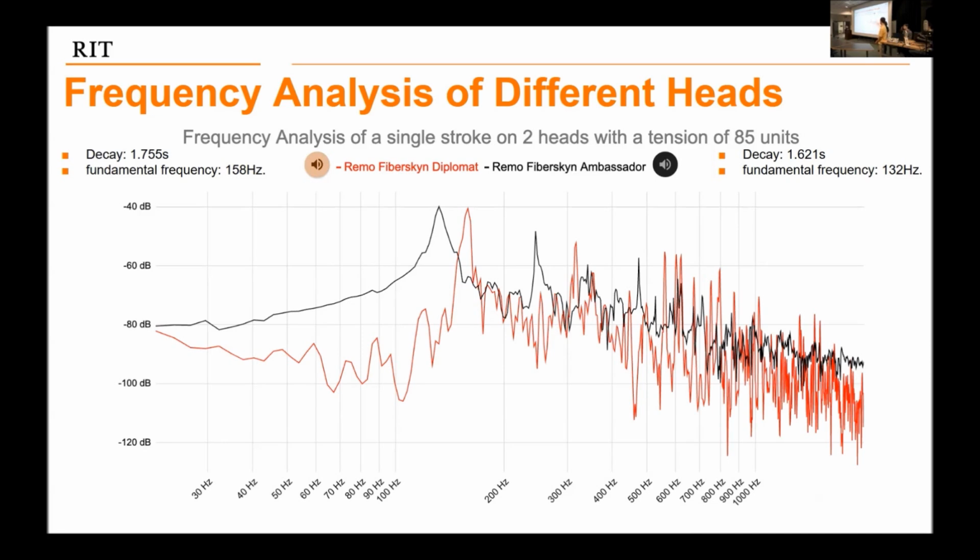So Audacity, I believe it was doing an FFT. Yes. I exported raw data points from what Audacity gave me into an Excel spreadsheet just so I could have a cutoff at like 2,000. Okay. Yes. Yeah, because Audacity does do roll offs. Yes. And you can pick your Hamming window, your windowing functions and all the other goodies.